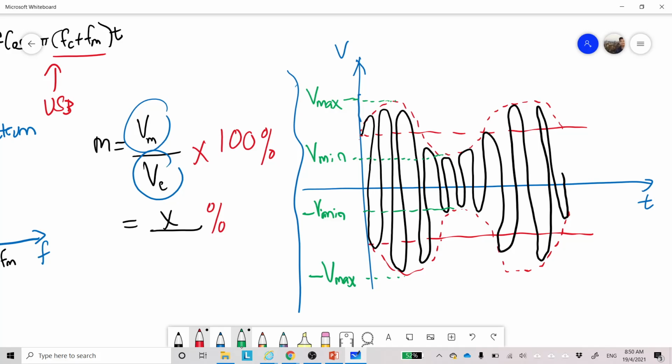So we transmit more than enough power to the receiver, while the information is only in the lower and upper sideband. That's why you will see later that double sideband full carrier is quite a waste of power, because we transmit the carrier which contains a large power but without any information. That one is in the power topic.